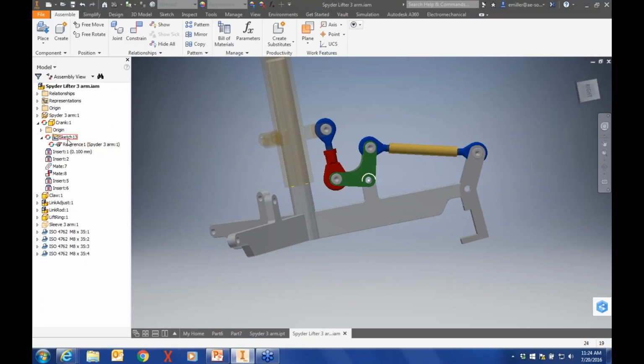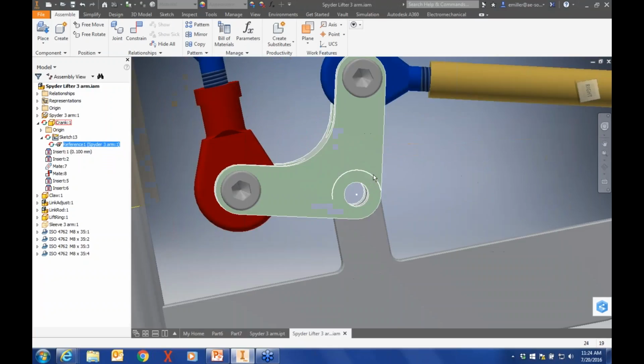Obviously, to remove those references, and that's something I really encourage too: creating external references is nice during the creation of a design, but towards the end, once you get to release that and allow everybody else to work on it, I really encourage you to try to remove these external references if possible. Maybe just create a sketch on that instead. That way the part can be independent on its own.